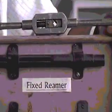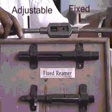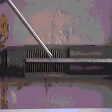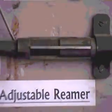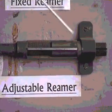Now the adjustable tap handle and fixed tap. This has 6 slots and 6 blades. It has nuts on both the sides. If we loosen the back nut, it moves down, the blade shifts downwards, so its outer diameter increases. And if we loosen the upper nut, the diameter decreases.